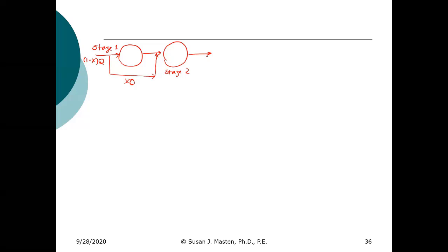And we can tailor a water to the hardness level that we want. Typically, we design this system based on a magnesium concentration in our treated water. So we need to calculate the split ratio.